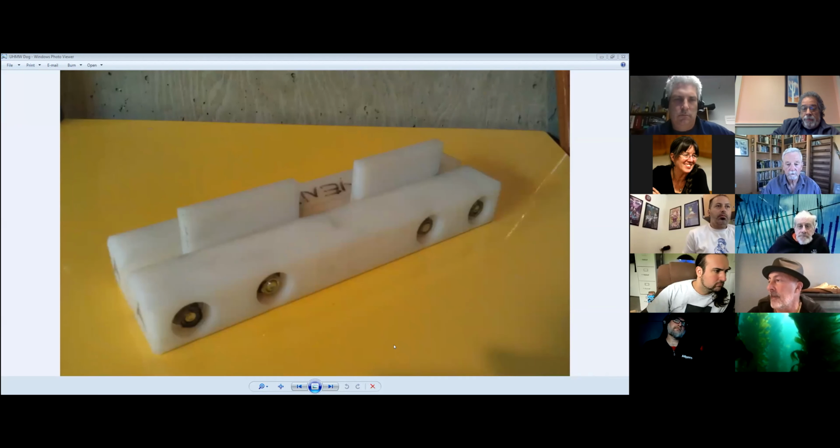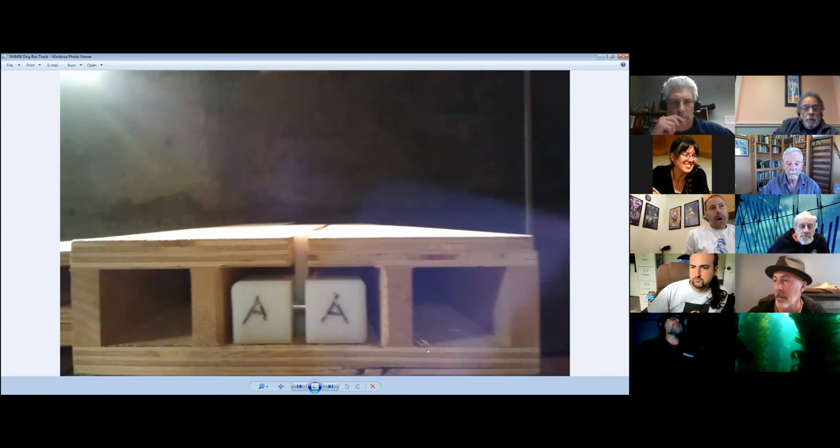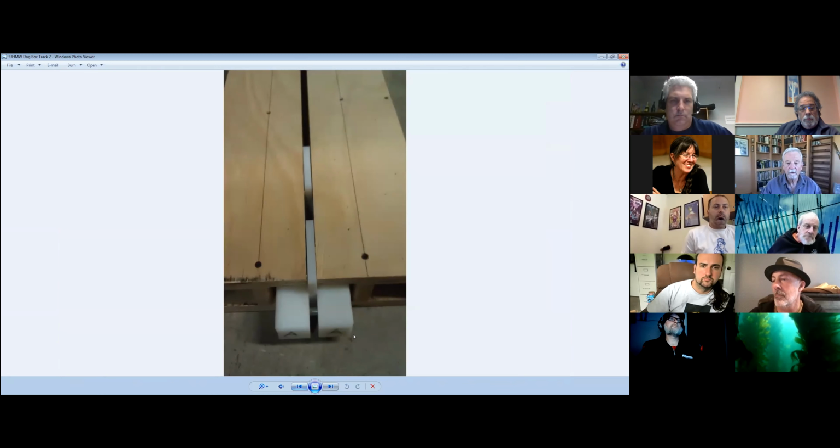Sure. So here's a dog that we use for our box tracks at San Diego State. Wrong slide. It fits in a box track. Really, a box track is a track designed for when we need to put a track down and we're using a platform deck, our standard platform height. This matches it. So we can slap a few platforms on either side of this and build a track into the system like that. In this case, this dog would be attached to the cable, not with friction, but with an actual thimble and the wire rope connection right there, swaged in. And you can see how it looks in the track.